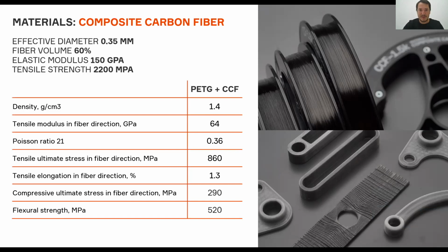Chopped carbon fiber filaments are just so much easier to print than regular PA. I'll never print anything without chopped fiber anymore. Yes, that's true when you are printing on plastic nozzle, but with continuous fiber, it is different. So it is also possible, but there will be much more issues in regards with the co-extrusion process.